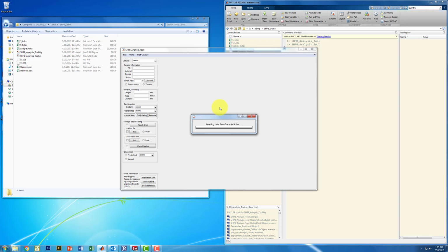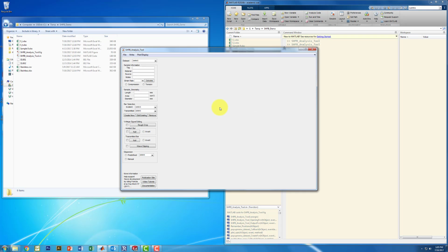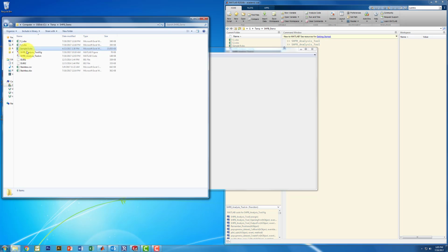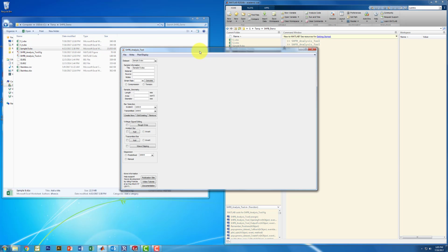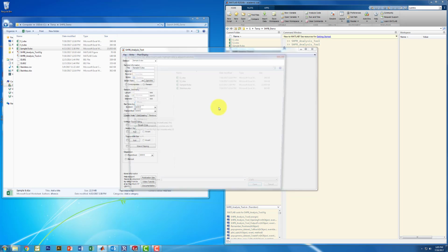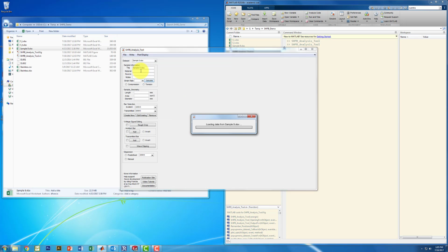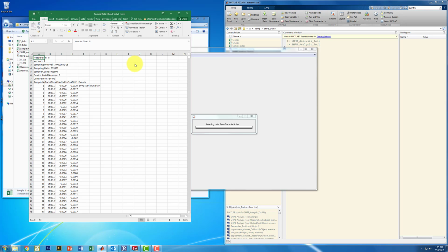Okay, so it's going to take those two columns of data that I've highlighted, and now they live right here. That's sample 9, that's this file, so it just pulls whatever that file's name is. If you want to have more information in there, say you had multiple strain gauges, multiple tests, you can do the same thing again. Let's go interactive. Do the exact same thing again, and it'll just put a _1 or _2 wherever you're at, so you have unique names every time.